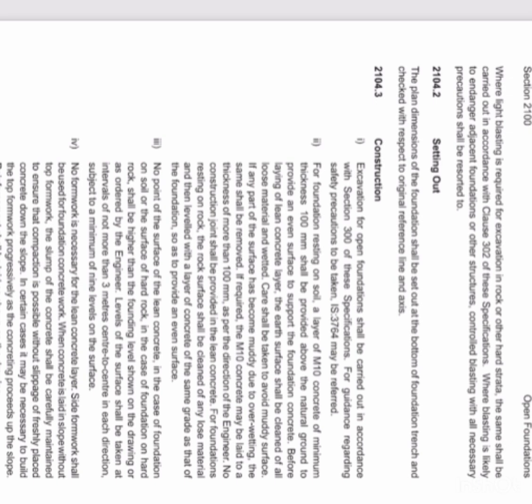The rock surface shall be cleaned of any loose materials and then leveled with a layer of concrete of the same grade as that of the foundation so as to provide an even surface. No point of the surface of the lean concrete in the case of foundation on soil, or the same on hard rock in the case of foundation on hard rock, shall be higher than the foundation level shown on the drawing or as ordered by the engineer.